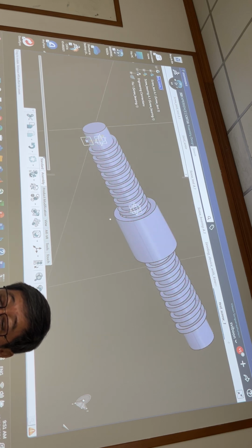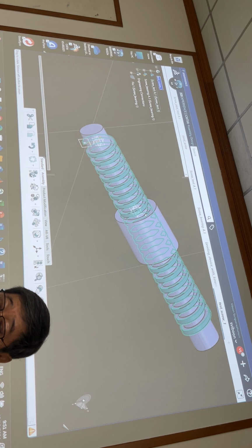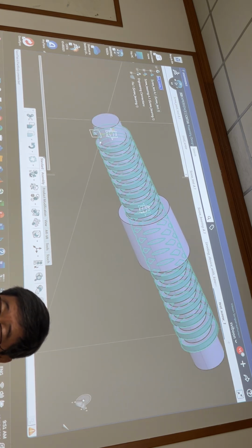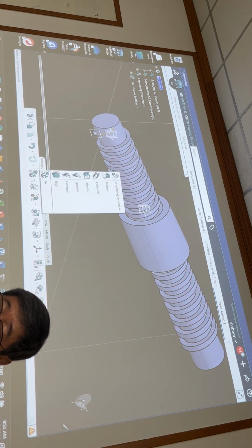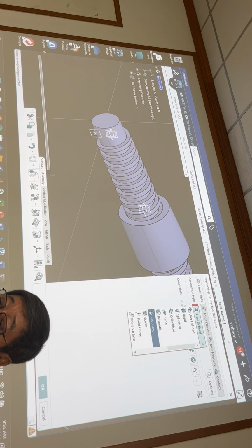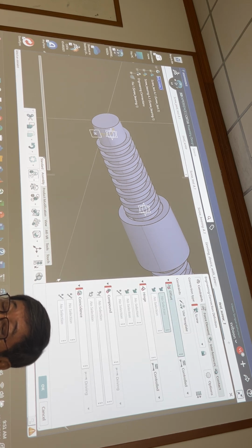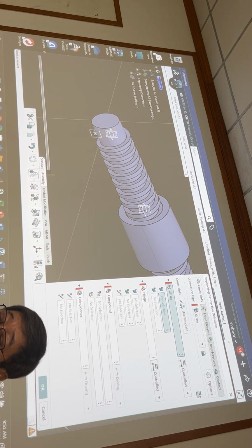Next, I want to assign a screw joint here, right? Okay, so you have this one, screw joint. I can use a template, yeah. Any connection? Look at this one, use screw joint. Select screw, this is fine. Boom. You get four of them, you see, right? Four of them. First of all, control. You see, the offset between this one. Select this one.